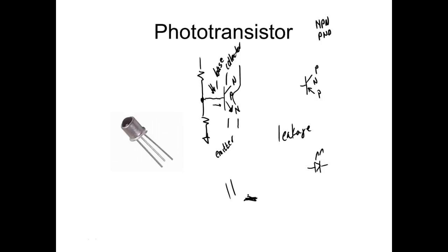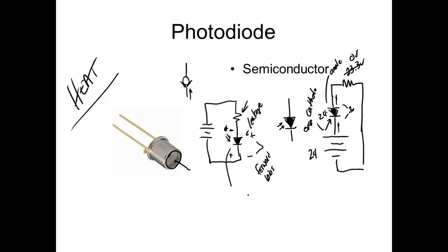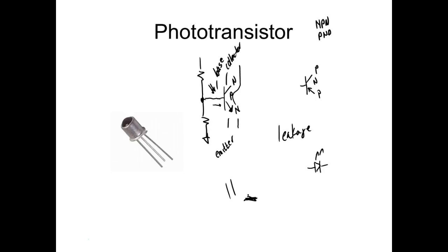So just about all our sensors now, like on this, odds are if you got a motion detector on your house, it's going to use a photoresistor. Anything where the light does not vary real fast will probably use a photoresistor. These are really, really cheap, right? Anything that requires a fast response time for a light sensor is going to use a photodiode or a phototransistor. The advantage of a phototransistor is we can use a very small current generated by the light over here on the base to control a relatively higher collector-emitter current.